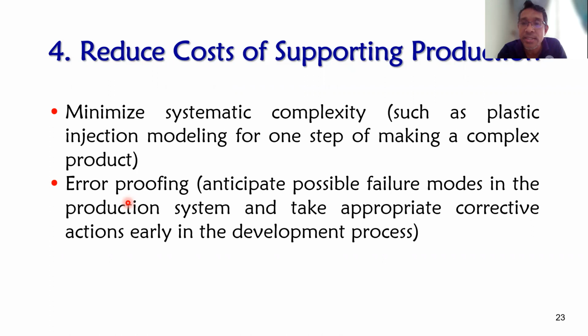So we need to think about that to make our foolproof jig to prevent mistakes in the Poka-yoke system. We can see also the direction of the screw. They have threads turning differently, left and right. So the product also has a mirror image, so the part is different based on that. So we need to differentiate using error proofing to anticipate possible failures during the production system.